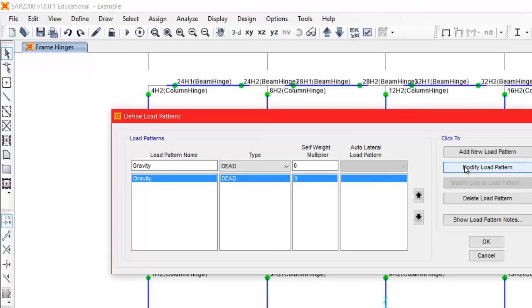You can leave it without assigning it, but again, because for this assignment you are given specific values, which could be taking into consideration some kind of splices in between, or some other material that you are not considering here, to be safe, use the ones you're given and set everything default here to 0.